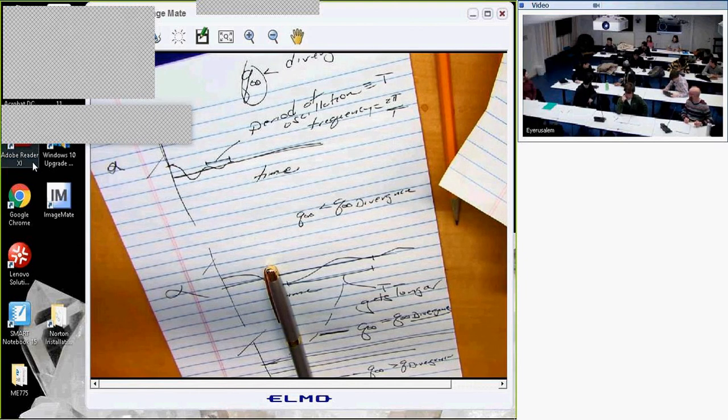I think in this case we are treating a 2D flat plate problem, but is there any 3D effect in reality? I think the lift coefficient will be different. And I mean, it's not 2 pi in reality. And is there any additional effect? Oh, absolutely, absolutely. Later on, let me draw a picture.